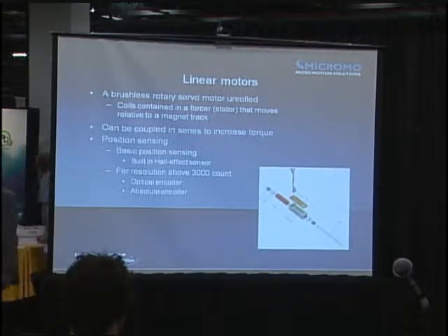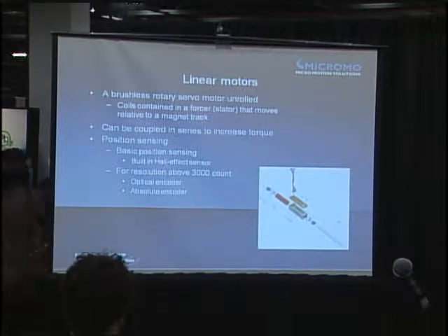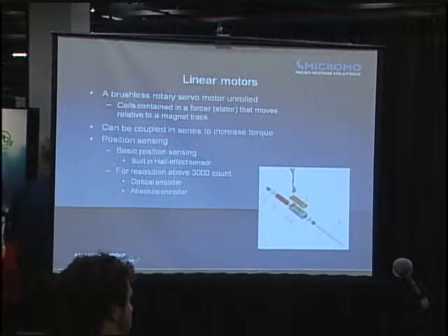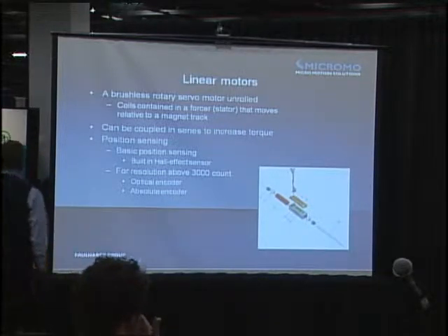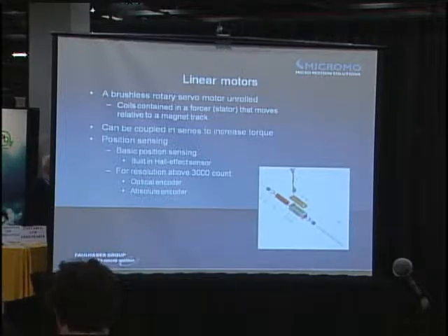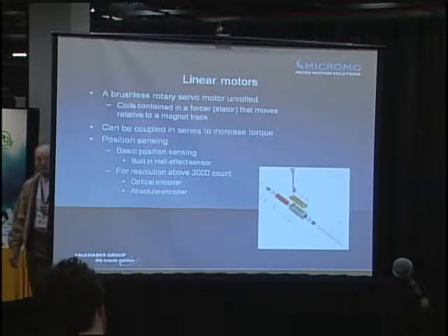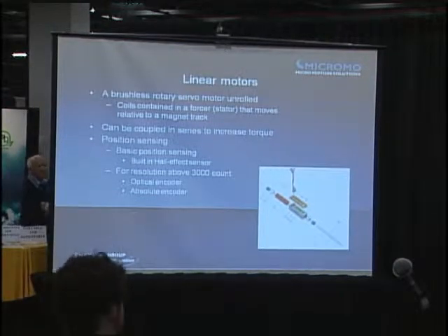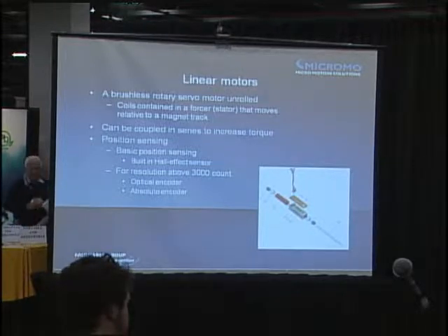And the size that you're looking at anymore, you can get down to like a 1/2 inch size on the square part of this function right here. Also, in this case, there's a positioning capability of like 3,000 counts over that movement, so you're getting down into a couple of microns of precision.